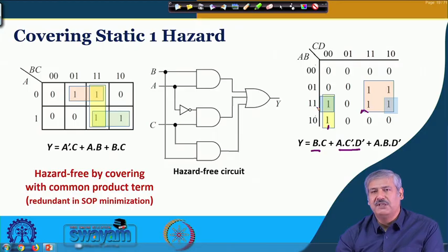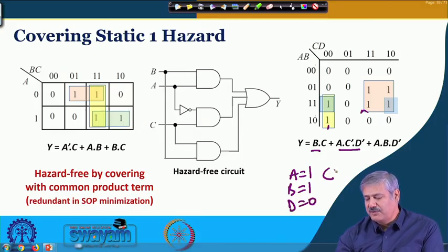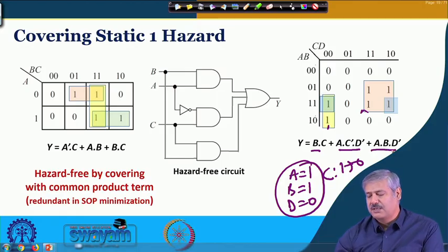So that is the A B D prime, and if you remember, that was the condition at the input side when A is 1, B is 1 and D is equal to 0, and C was changing from 1 to 0, the glitch was occurring. So by having this A, B, D prime connected here, for this particular case when the glitch could have been there, putting such an additional 3 input AND gate and connecting to an OR gate, right, you are suppressing that glitch.